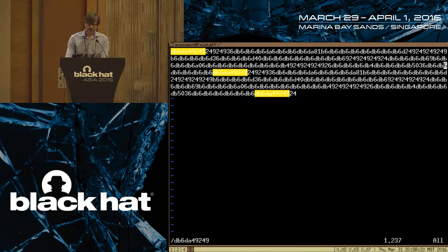Now, how far into this? If I look at my counter at the bottom right, 250 characters in, I get a repetition. And then the next one here is at 499 characters in, right? So I have a consistent repetition every 249 characters. So I'm seeing that what Yardstick 1 is detecting as one packet is really multiple repeated packets.